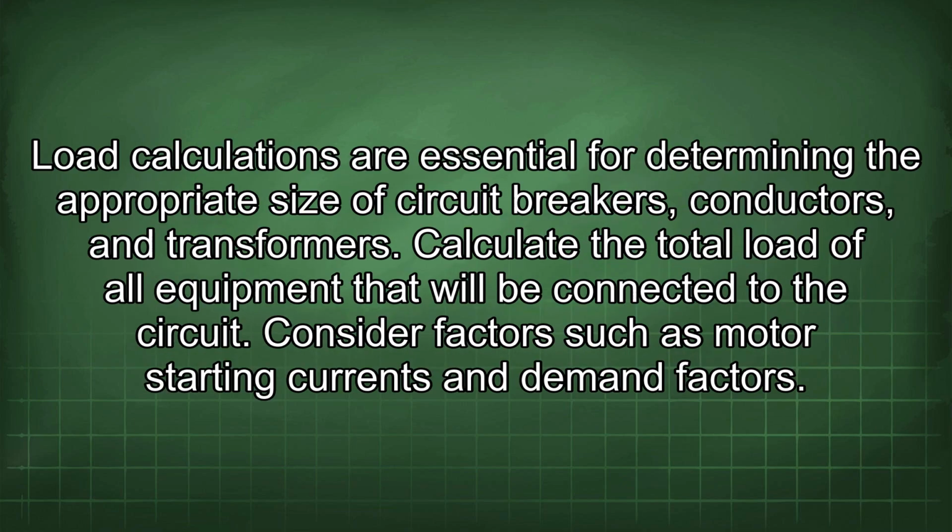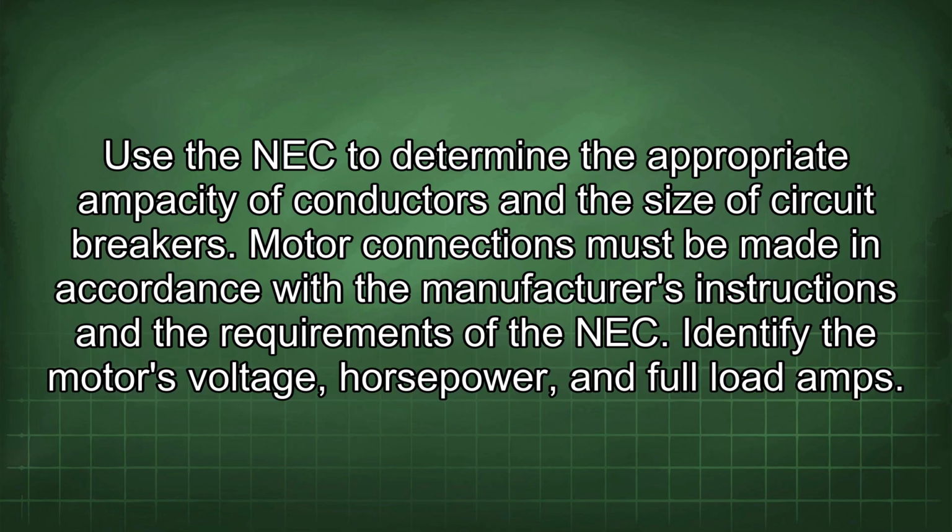Load calculations are essential for determining the appropriate size of circuit breakers, conductors, and transformers. Calculate the total load of all equipment that will be connected to the circuit. Consider factors such as motor starting currents and demand factors. Use the NEC to determine the appropriate ampacity of conductors and the size of circuit breakers.